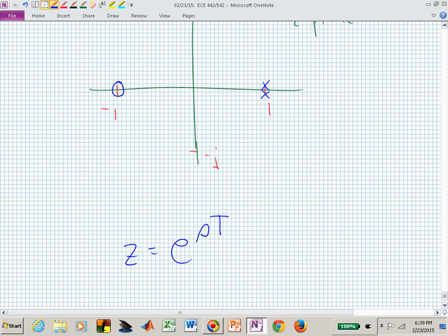That point at 1 on the unit circle is where we find our frequency response in the Z-plane, consistent with the imaginary axis in the S-plane, and the origin in the S-plane, S equals 0, is similar to this point at Z equal to 1.